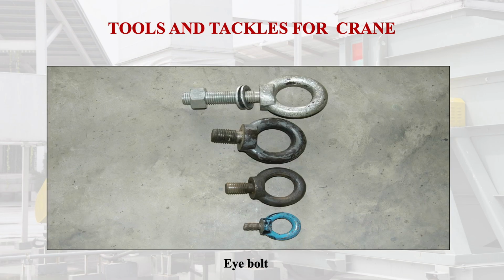These are eye bolts, normally used in industry for lifting small items where the job or the article or the object has some threads. These eye bolts are fitted in the threads, and then either a chain or wire or some special belts are inserted within these eye bolts, and the job is moved, shifted or lifted from one place to another place. But the important thing is that due to this load concentration, or you can say stress concentration, it may fail in between the operation.